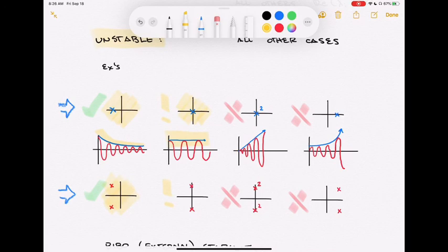We could do the same thing for the pair of roots, right? Now there's no exponential decay, so the envelope for that oscillation doesn't decay. It just sits there and oscillates like a sinusoid. In fact, this is exactly the kind of characteristic roots we'd expect for a system that was supposed to function as an oscillator. If you did an LC circuit, just put a capacitor in a loop with an inductor, nothing else, and they were ideal, they would behave exactly this way. You should have seen that in circuits. They would just cause an oscillatory output, a cosine output that neither decayed nor grew. Marginal stability.